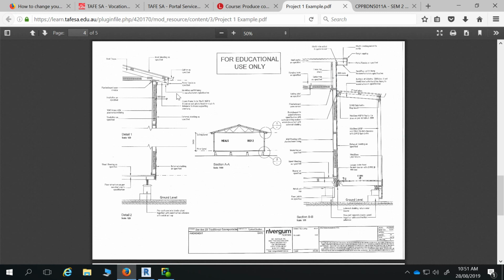We don't have to add any detail lines. All we're going to add in is obviously these detail elements being the purlins, some insulation, which is just that insulation tool, insulation in the wall, and then your top plate, bottom plate, and noggin.